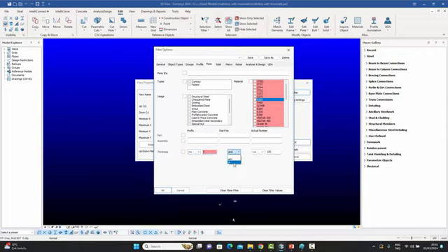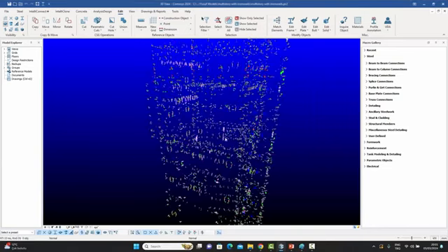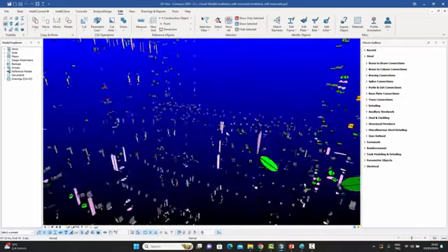you can put an "and" or "or" between them, and less than, for example, less than or equal to 10. So you have these operators of equal to, not equal to, or less than, and you can use all of them in combination with the first parameter and the second parameter. So now it's going to show me only the plates which are between 5 and 10 in thickness in millimeters. And if I say okay, then it filters out those plates,